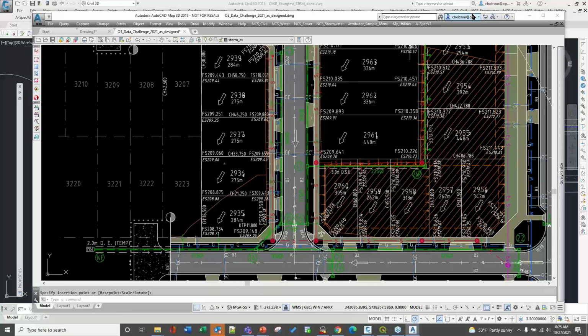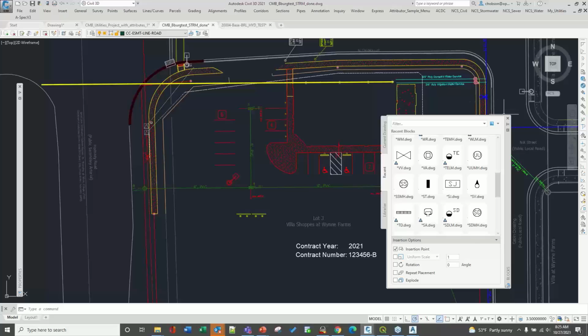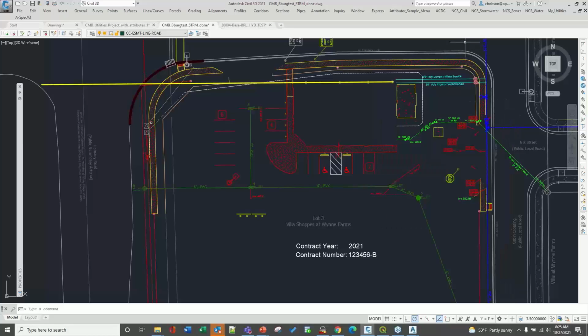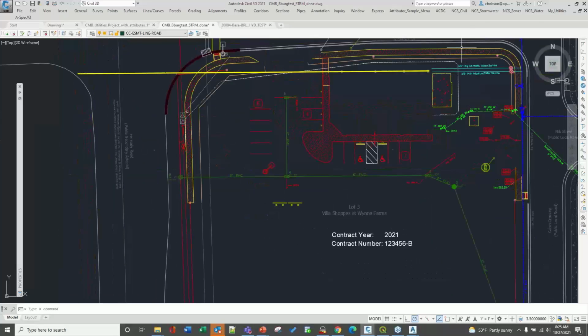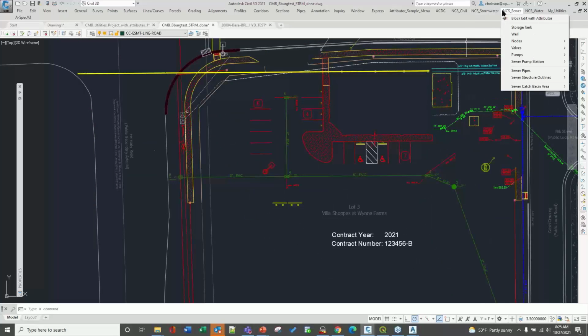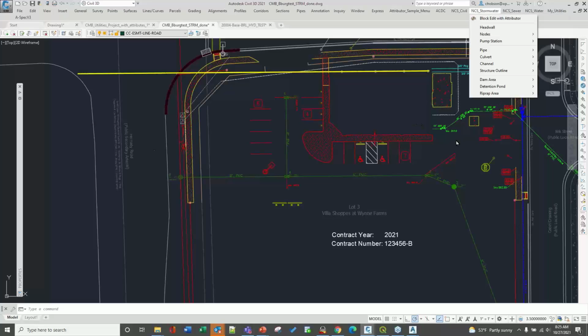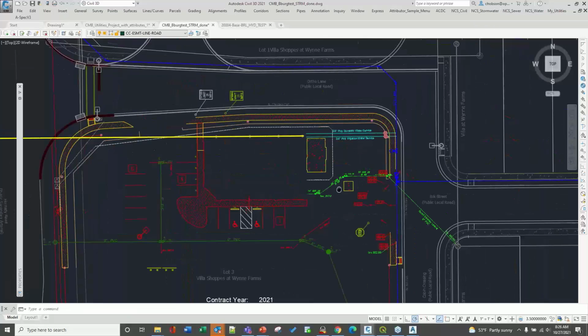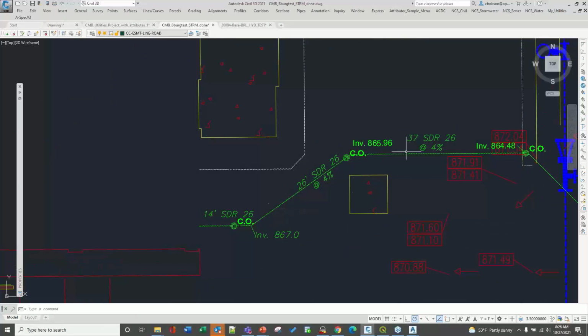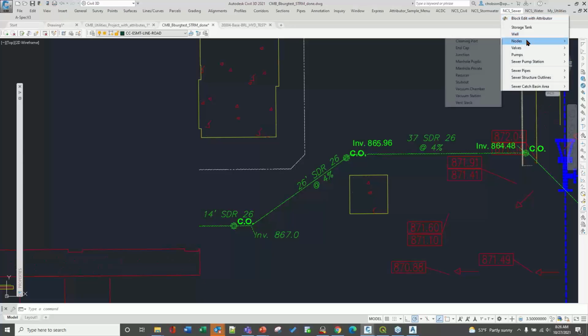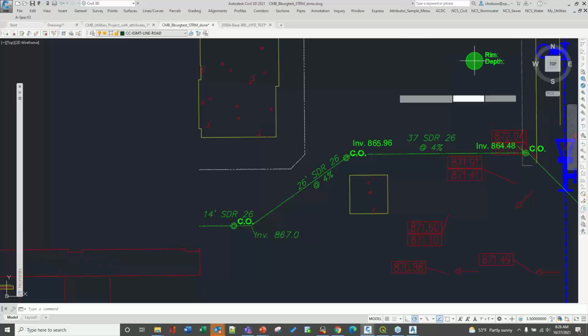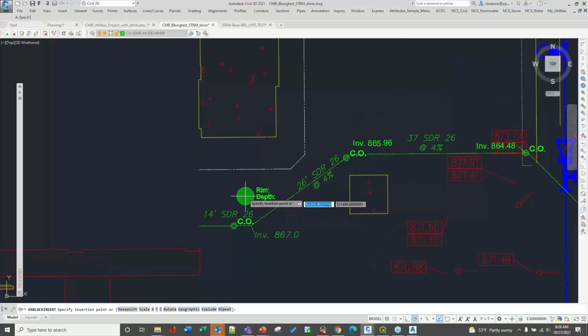So one of the things we've done at OpenSpatial is create an AutoCAD plugin, and it's free on the store, and you can just go there. Now we put that on the menu, so that if somebody wants to put in an asset, they can go in and say, let's build this out and put a manhole in. I can go to the menu. That's going to get me the layers already, and it's going to insert the block, and I'll just put it over here for clarity.